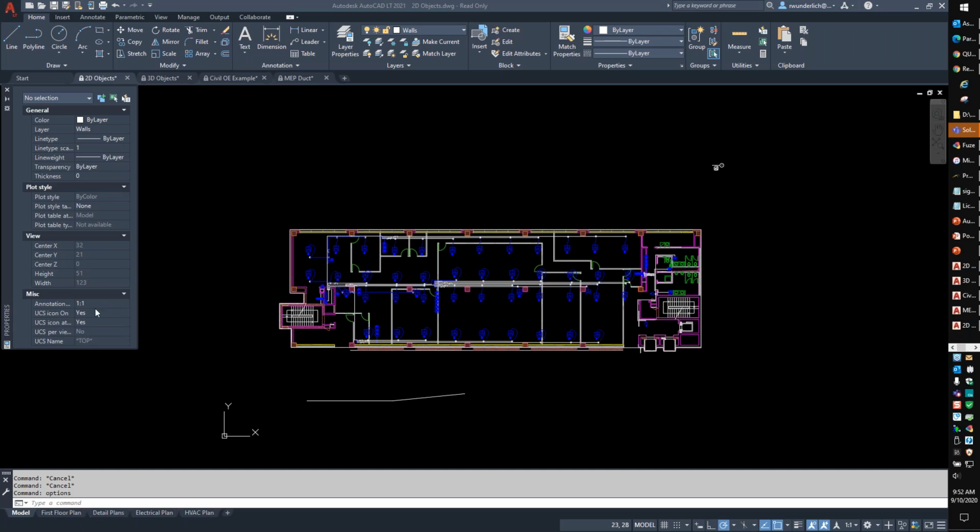Can ArcGIS objects be imported, edited, and exported back to ArcGIS? In plain AutoCAD or AutoCAD LT, no. You're going to have to go through at least Map 3D in order to do that, because Map 3D does support full ArcGIS connectivity. You are not going to have access to any of the major data inside of plain AutoCAD, so you won't see any of the miscellaneous data that's usually tied back into the ArcGIS information.